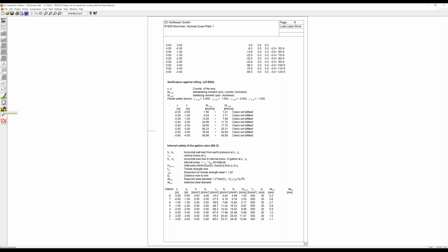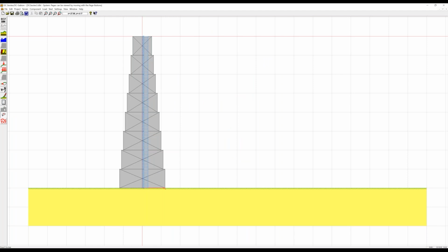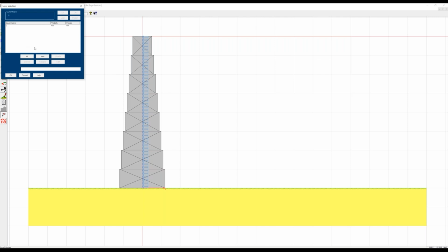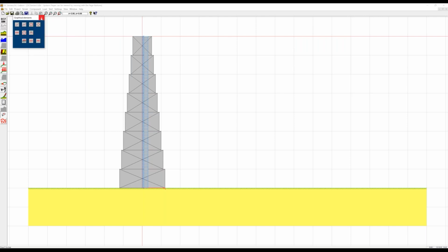Okay, so far for the different types of the wall, we have some more functions for creating or for editing the graphics that we have in the program. Here, this is some list of graphics functions. We can add here graphics, we can add text, we can have measurements. We can as well import DXF files. So you have graphics in the background and use it for the construction of the soil layers, for example, or define of the different layers. And we support all the layers of the DXF, for example. You can switch on and switch off different graphics layers in this construction here.